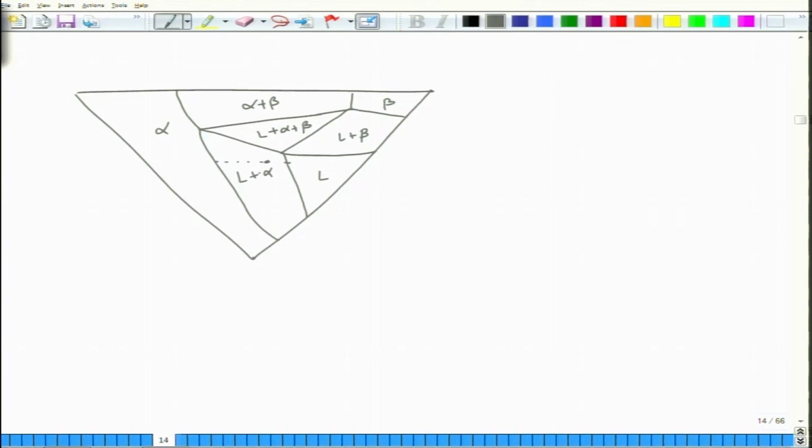So, you can draw the tie lines to determine the composition of alpha and the composition of liquid. This is the X alloy composition, and the ends of the tie line will give you the compositions of liquid and alpha, and from this you can determine the percentage alpha and percentage liquid by applying the lever rule.